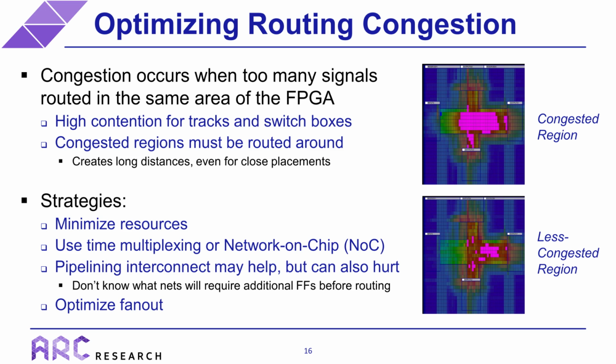So now we're going to spend a few slides talking about how to deal with that very common bottleneck. I'll illustrate this in more detail in a future exercise, but the current recommendation is when analyzing interconnect delays in a timing analyzer, always look for nets that might have a high fan-out. This is a very common timing bottleneck, so it should be one of the first things you look for when trying to minimize interconnect delays.